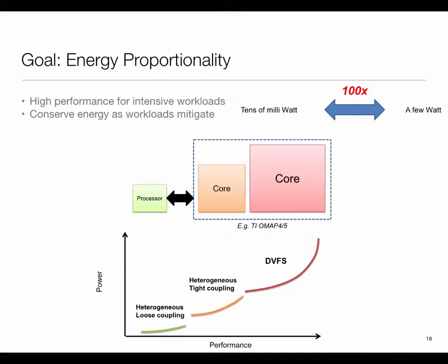If I were to characterize Snapdragon in this space, Snapdragon does not have big.LITTLE. It only has a bunch of big processors, and then a bunch of loosely coupled processors, DSP and Cortex M3. If I look at Samsung's chips, they have gone for multiple big.LITTLE processors. If I look at Apple's, and I'm ignoring that almost every processor in the mobile space also has a GPU, which you can think of as a specialized, loosely coupled processor, it again is more like Qualcomm's Snapdragon, namely multiple big cores and a loosely coupled little core, and then of course the GPU.